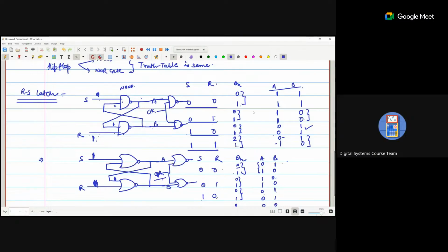So when you go through the content, we will discuss in more detail in the Wednesday class. So that is a brief idea about what a sequential circuit is. A sequential circuit uses a clock for synchronization. In the sequential circuit, first is the latch unit. The latch is level triggered. Then we go to the flip flop. Flip flop is basically edge triggered. With the help of flip flop, we can design a counter, register, then FSM, finite state machine. So we are going to discuss all these things in the next 4 weeks, 9, 10, 11, and 12.